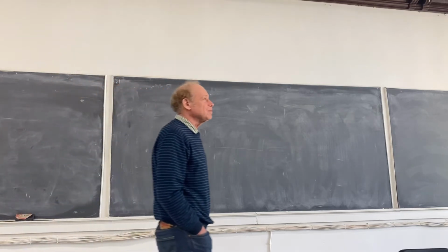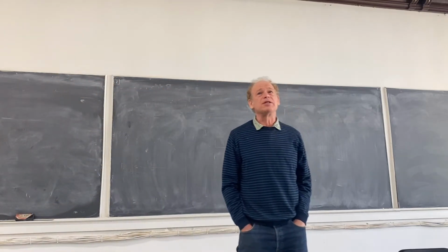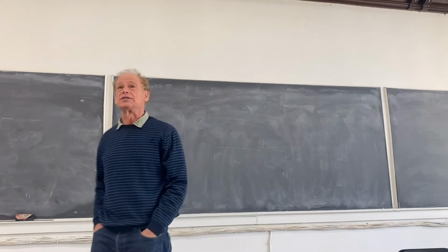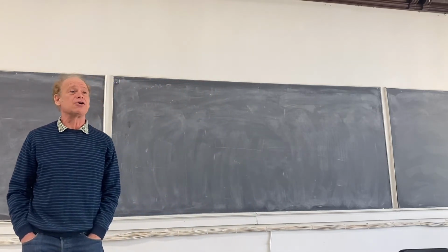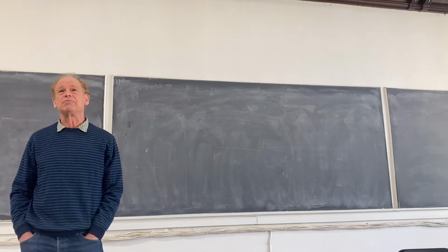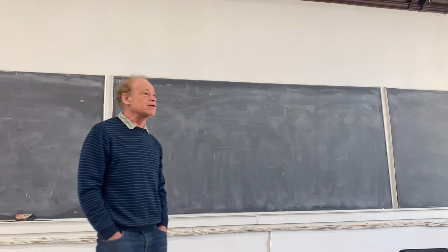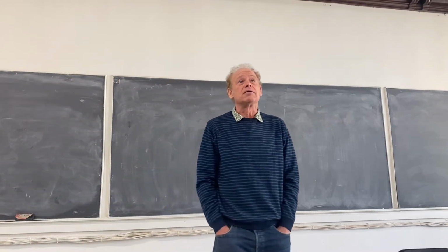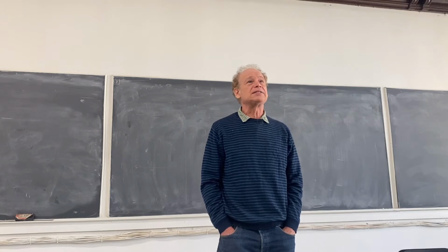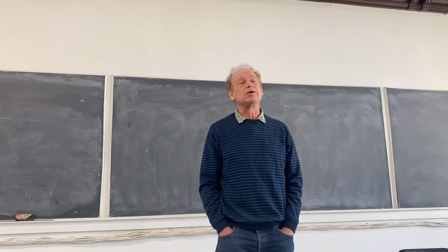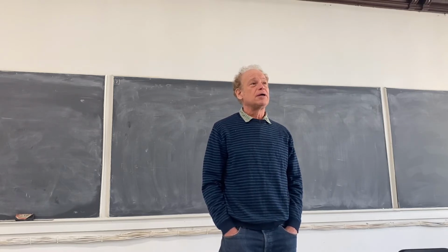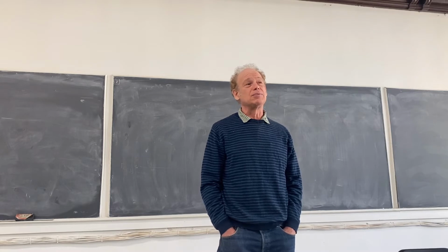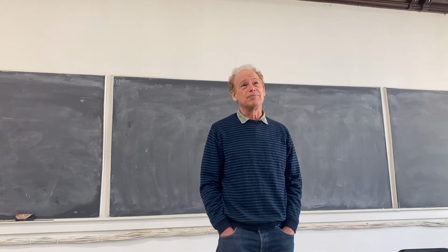When you do an energy balance, every term in the equation has to have the same units. When you do any balance, any equation, every term has to have the same units. Some people in the energy balance just put a reaction rate in. But that's in units of moles per unit volume time. And the rest of the equation was in units of energy per unit time.